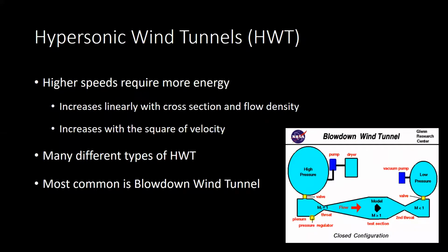So now moving on to hypersonic wind tunnels. I'd like to revisit the power that I keep talking about. To give you an idea of how much power we're talking about, just imagine doubling your cross-sectional area or maybe even doubling your flow density. This results in doubling your power. But in the case of hypersonic wind tunnels, if you want to double your velocity or double your Mach number, this would effectively quadruple the power required.